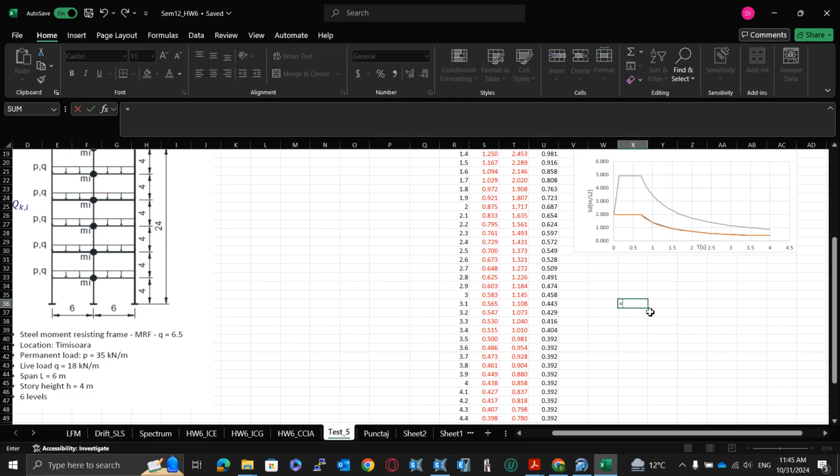Now, you have the value for phi we discussed, okay? V is 1.35 multiplied with 4.5, it was the permanent load. I think 4.5, yes? Permanent on all levels. This is just very simple. Plus 1.5 multiplied with 3, 2.5?